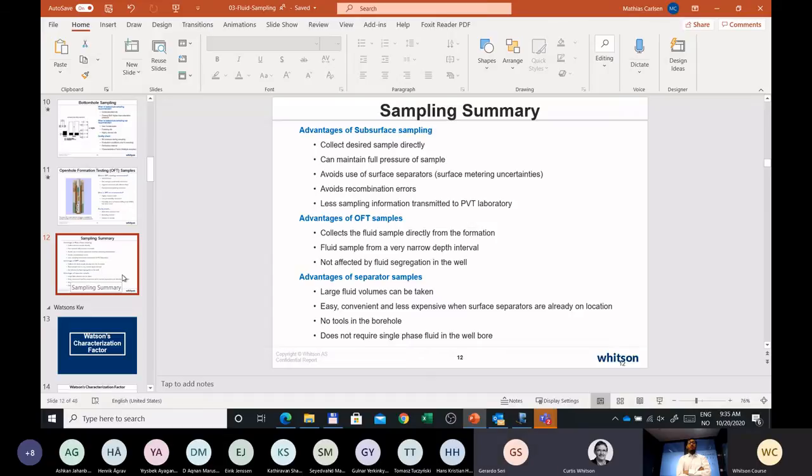If you equilibrated that with any oil sample from below that you collect independently, and put it in the PVT cell at GOC conditions, then what you found, and we showed it in the paper, is that you pick up all these small amounts in exactly the right proportion into that reservoir gas in the PVT cell.